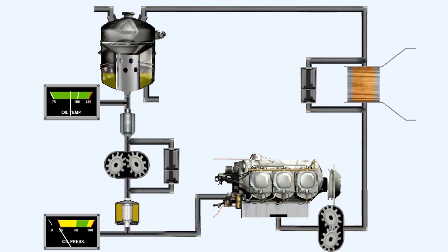If the oil pressure falls suddenly to zero, then perhaps the reasons may be a bit academic. After all, if the minimum oil pressure cannot be maintained, then the engine must be stopped to prevent damage, and there is probably not a lot you can do about the problem. Nevertheless, the probable cause is either failure of the pressure pump or a total loss of oil.